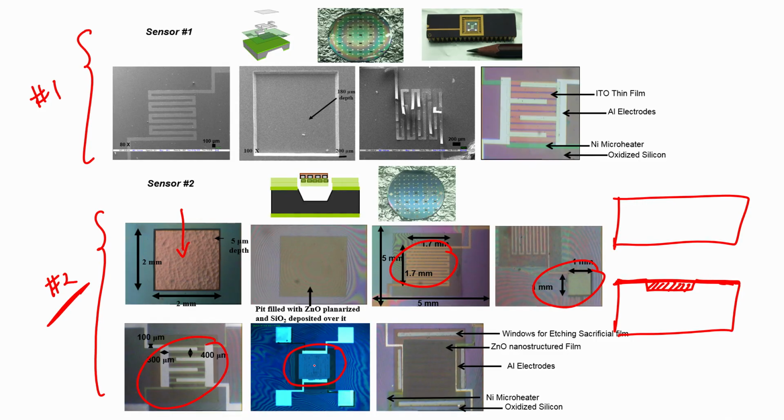Now, this is a nanostructure of zinc oxide, that is why you cannot see the interdigital electrodes below it. Then we open windows on 4 sides and etch the zinc oxide that we deposited initially. This zinc oxide will act as a sacrificial layer, do not worry about it, we will discuss this in the class where I will show how to fabricate this particular sensor.